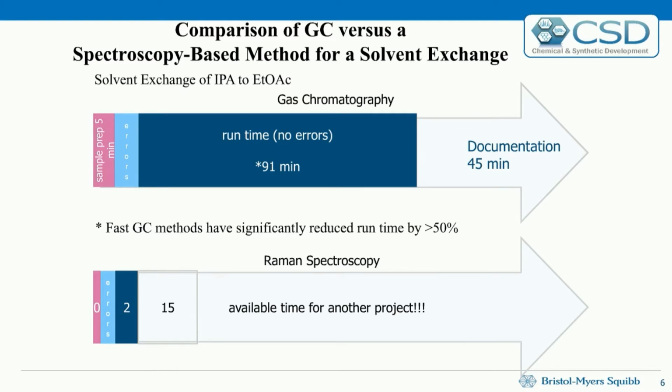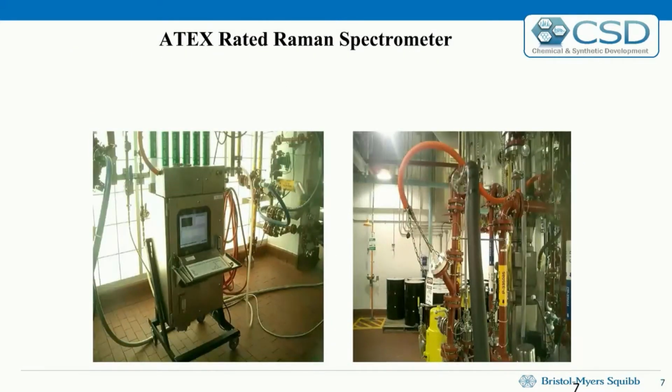With the Raman spectrometer, we tend to run our assays in about a 2-minute time scale, and we save a lot of time, so it enhances our productivity. And that's just for offline analysis, as I showed you shooting through a jar. We also pick instruments, whether it's FTIR or Raman or near-IR, that are ATEX rated, so we could use those in various countries, and of course UL rated for applications in the United States.